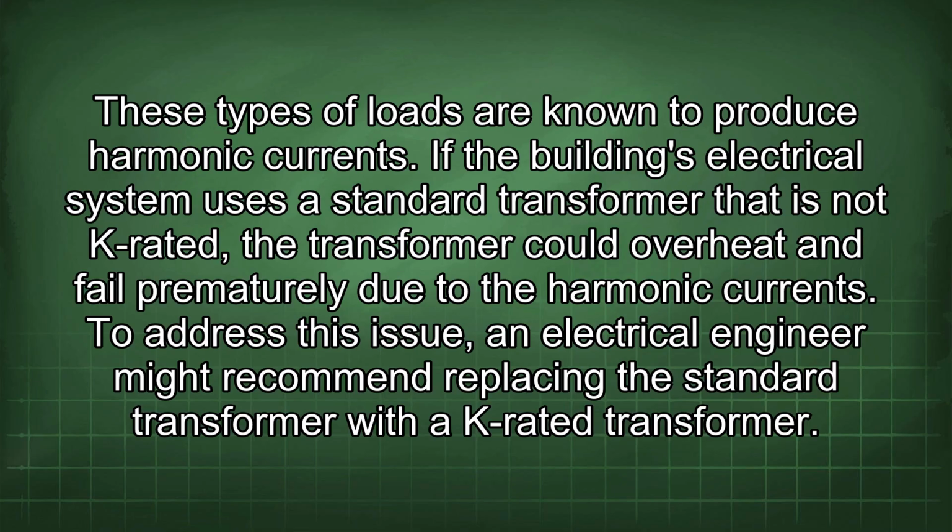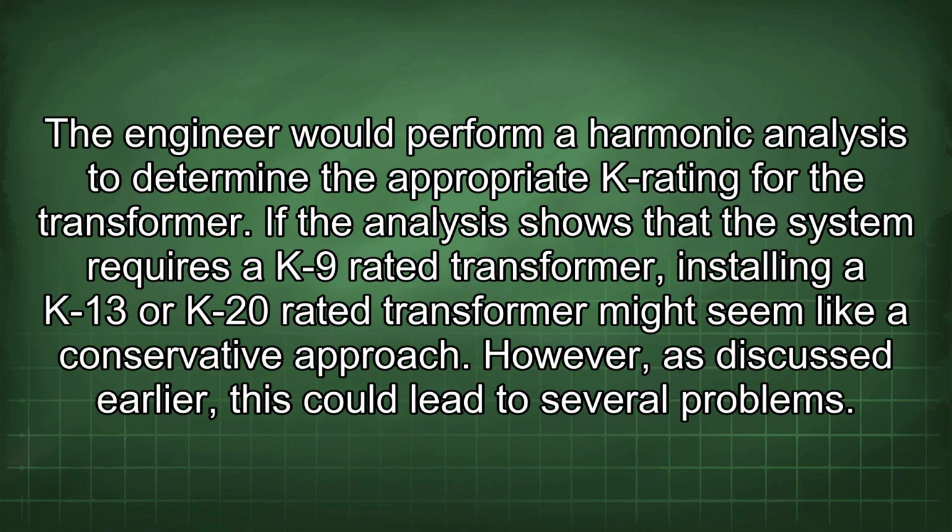If the building's electrical system uses a standard transformer that is not K-rated, the transformer could overheat and fail prematurely due to the harmonic currents. To address this issue, an electrical engineer might recommend replacing the standard transformer with a K-rated transformer. The engineer would perform a harmonic analysis to determine the appropriate K-rating for the transformer.